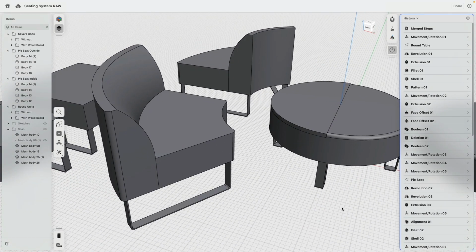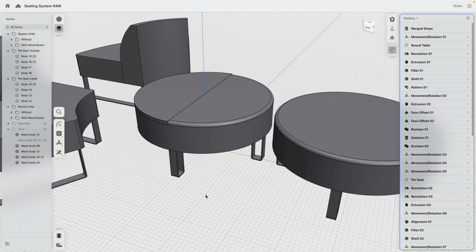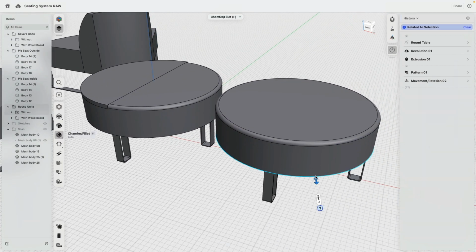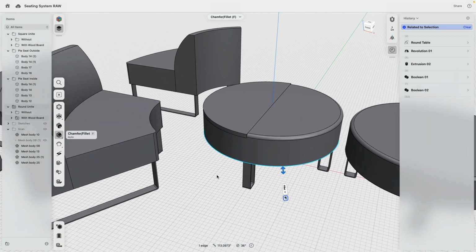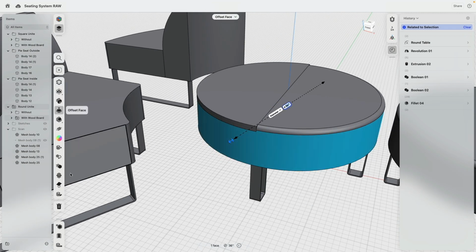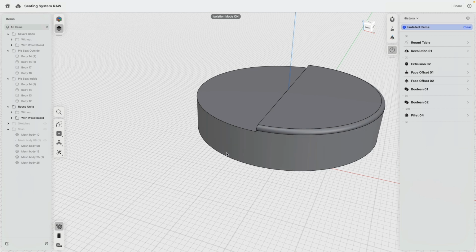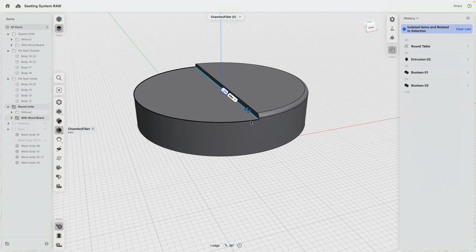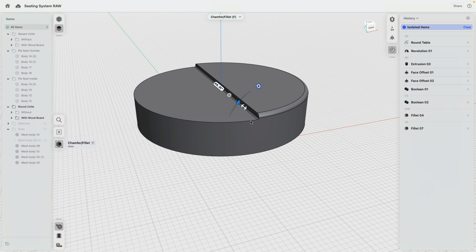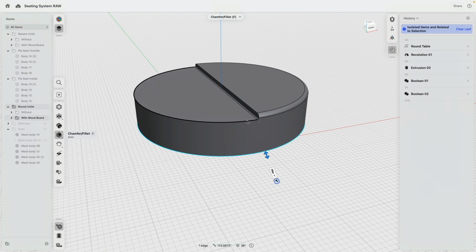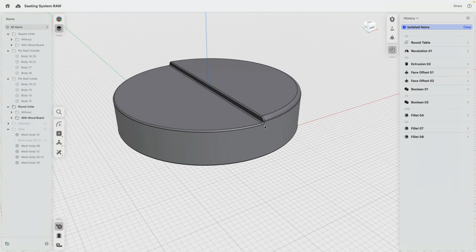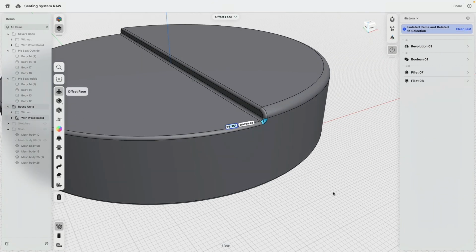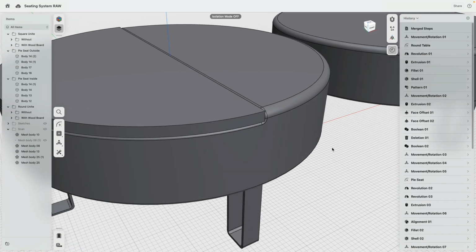Then, because we did basically all the big roundings, this is we said 0.75, 0.25. We make this tiny. Let's select this one and isolate, because I will go to here and say 0.25. That's the inside. Then I go to here and say 0.25. Very good. Because I rounded this edge first, I got this really nice detail here. Unisolate.